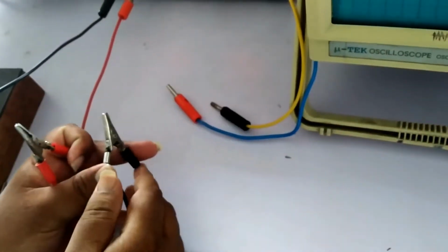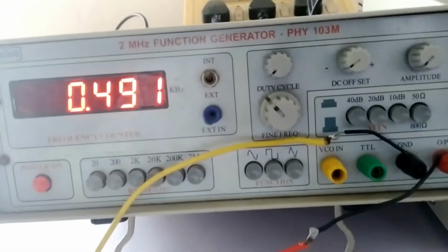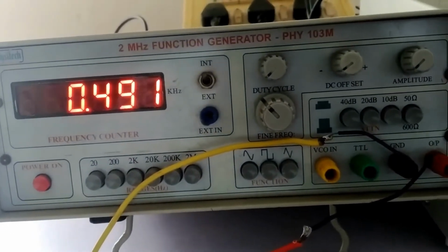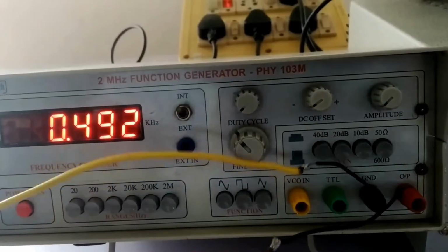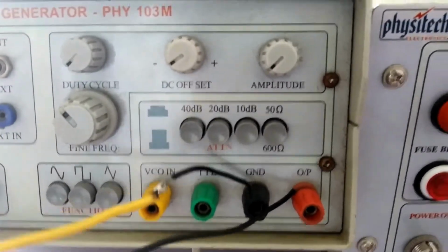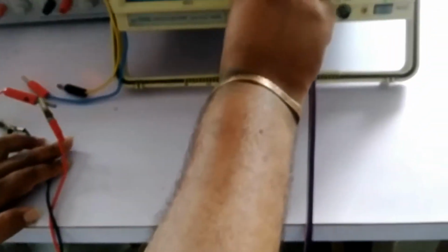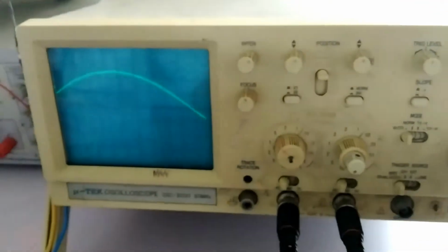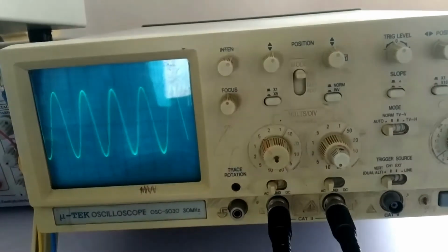Similarly, we have to set the modulating signal with the function generator at around 500 Hz. The modulating signal is a low frequency, and the amplitude is around 2 or 3 volts. We will observe the same thing in this case, and the output can be taken from the red pin and the ground pin, the black color. You can observe it in the same channel, because as I mentioned, the amplitude is very low. So here I have to set the amplitude, and even the time per division we have to change, because it's a low frequency and high time period.